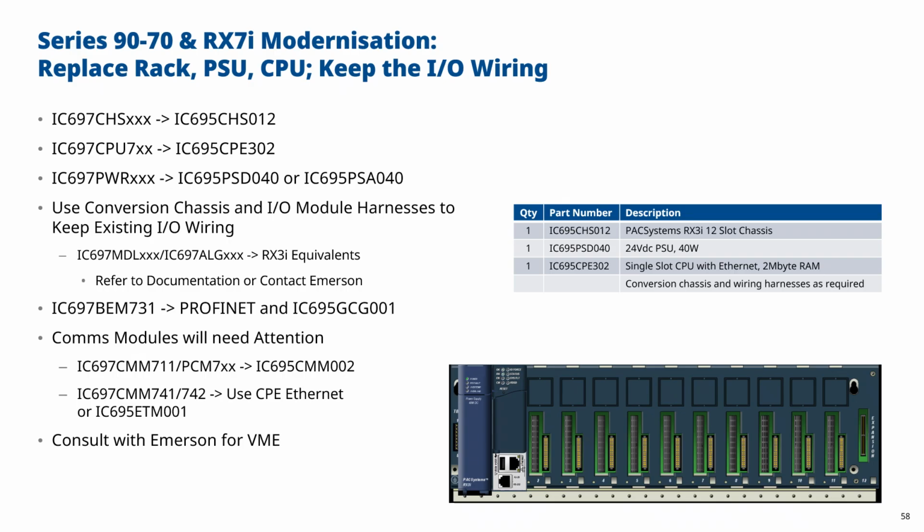Where it can get very complicated is with VME. One of the points about the 9070 and the RX7i is they used a VME chassis which allowed easy integration of VME modules. And at the time of the 9070, in the early days of the RX7i, there were several hundred different VME modules around. Some of those were I/O modules, some of them were motion control, some of them were communication modules. There were even embedded IPCs that could be embedded in the VME backplane.